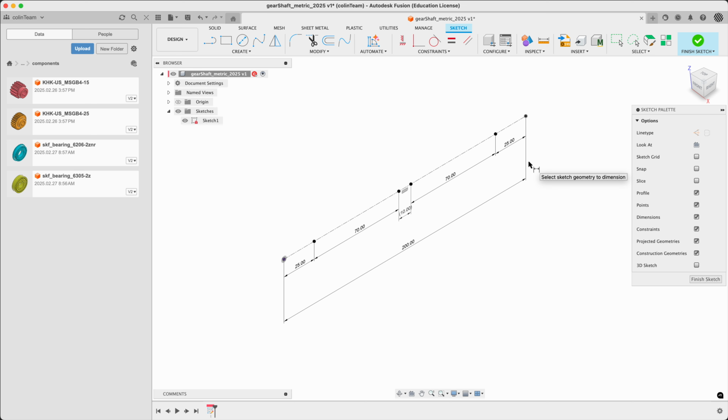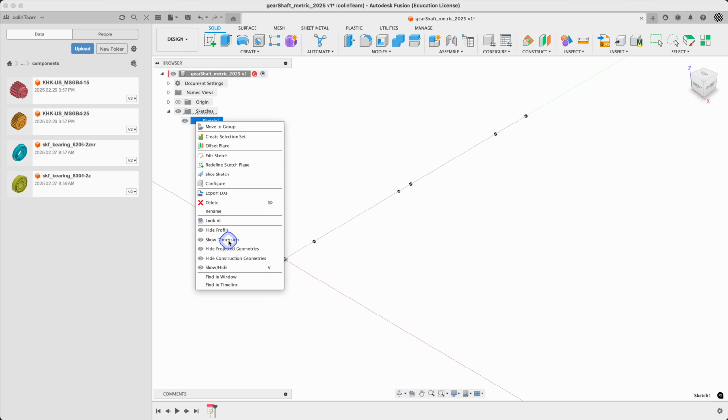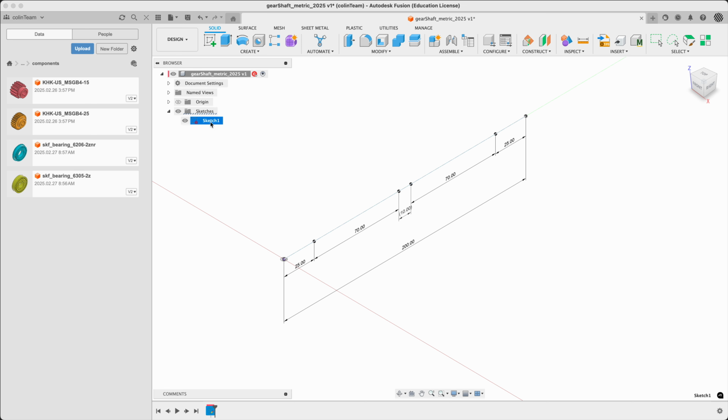It's really tempting right now to just start placing. We don't know where to place, so we're going to try placing them in a rough fashion, and then draw a shaft underneath in this same sketch, and then lock the components into place so they move with the sketch. That's the plan. So there's our midline, really boring looking. Let's have a look at the dimensions, so show dimensions. And I'll give this a name, layout shaft.